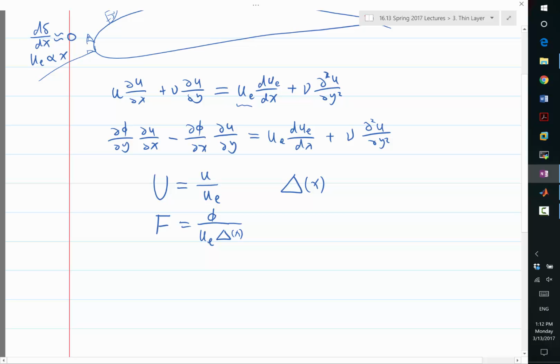Right? So with these two, let's start to, okay, so the delta x is used to non-dimensionalize y into our unit eta. So eta is defined as y divided by delta of x. And let's keep the x direction to be as it is, and let's just define xi to be exactly equal to x. Yes? In this case, is UE also a function of x? UE is also a function of x. Exactly, right. So let's write that down so that we don't forget.